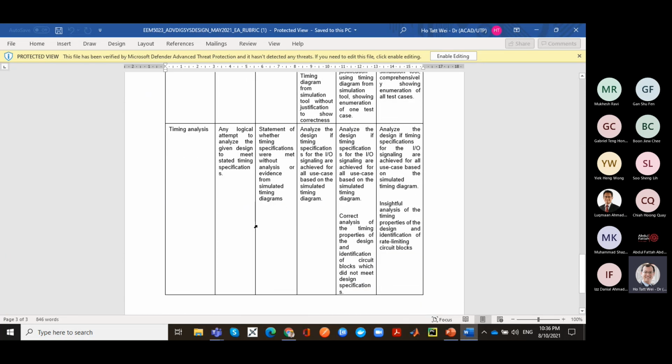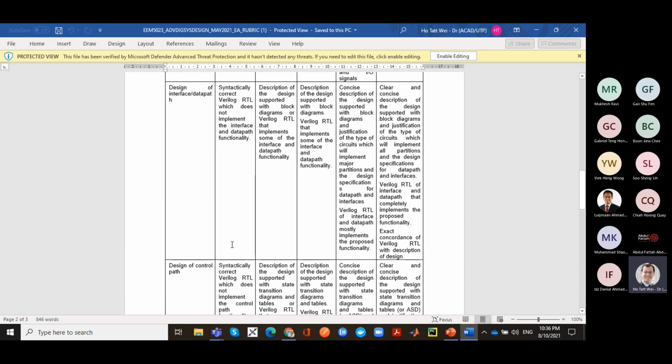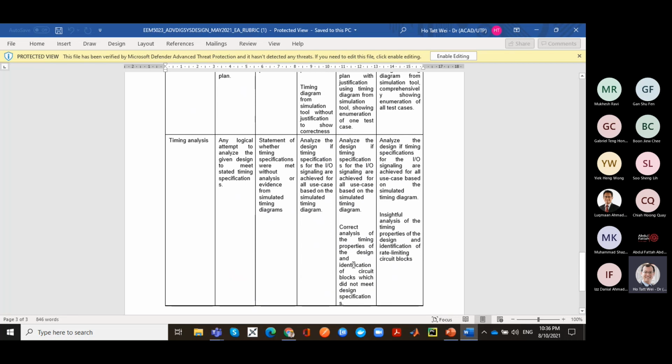And then the last one is the timing analysis. This is more of looking at the correctness of your circuit, right? So the correctness of the circuit, I would do a basic grading under these two rubrics. But sometimes when you're starting to design these things, you will find that the most difficult errors are actually the timing errors. You might actually get the correct output sequence, but maybe you're off by one clock cycle. Or you've forgotten to factor in the clock cycle. Some of these problems will come up, especially like the SDRAM one.